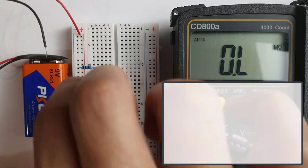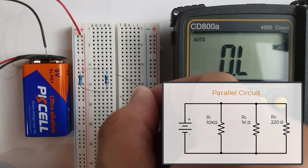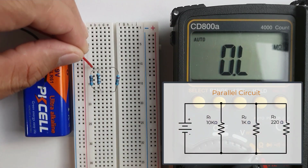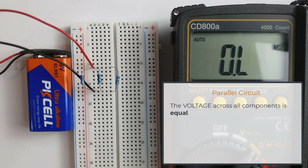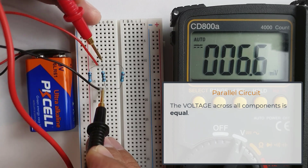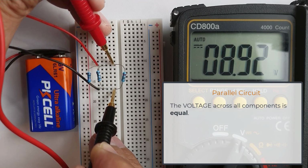Now, let's implement this given parallel circuit based on this diagram to understand how it works. So, I'll connect these three resistors in parallel like this. Then we have a 9-volt battery as a source. So, I'll connect the positive terminal of this battery to this node and the negative terminal to the other node. Now, the principles in a parallel circuit are as follows. First, the voltage across all components in a parallel circuit is equal. We can verify this using a voltmeter and measure the individual voltages across each resistor. And as you can see, regardless of the resistor's value, the voltage across is the same.